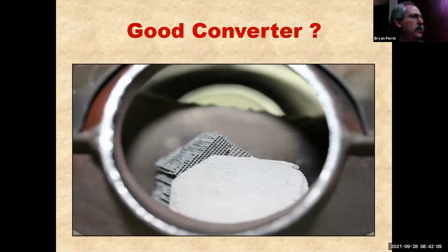Yeah, and so the two things that cause it to fracture like this, most common is overheating. The second can be impact. So impact can also be if the catalytic converter is not broken in correctly. When we replace a catalytic converter, we actually have to break that new converter in. In the service bay, we'll take it up to about 2,500 RPM and wait until you get a really bad smell, kind of worse than rotten eggs. That lets you know it's broken in, because there's a code on top of here.